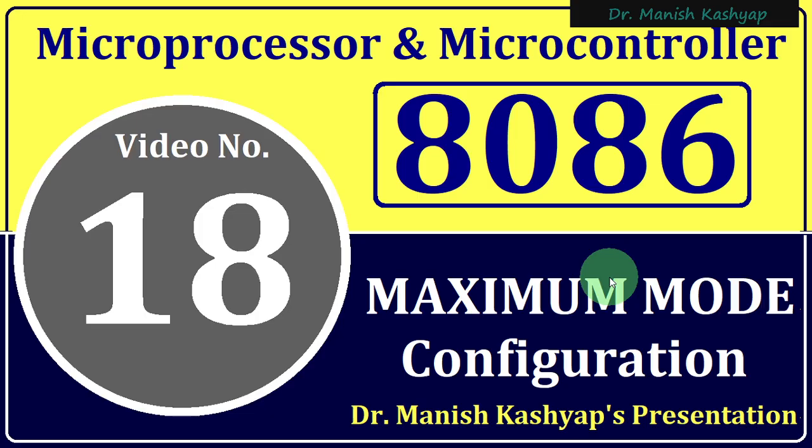Similarly, there is another mode in which various other processors can also be coupled with this 8086 microprocessor, and that mode is called the maximum mode of the 8086 microprocessor. Maximum mode, as we have also discussed earlier, is used to interface several other things like the 8087 math coprocessor. Then there is an input output processor, etc., which we are going to see. So there are various things which can be coupled with the 8086 to enhance the capability of the complete circuit that we have constructed, right?